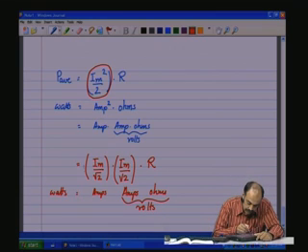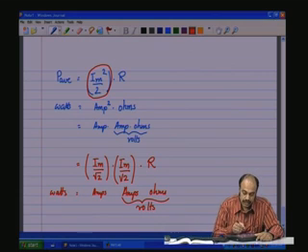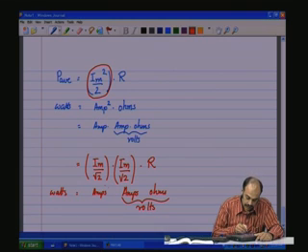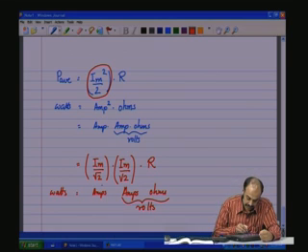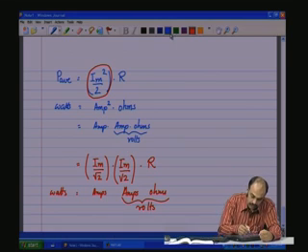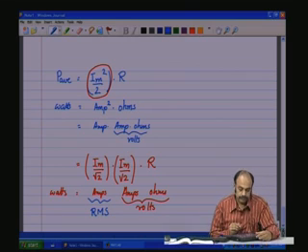Now, this current, which is equivalently producing the joule energy loss across the resistor, or which is basically the energy that is put into the resistor, is the equivalent current component that is the power giving or power generating, and this we call the RMS current.